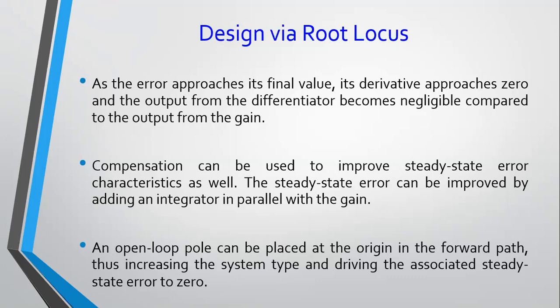In previous chapters, we had one section where we looked at transient response, which we just looked at. There was another chapter where we looked at steady state error. If you want to modify a steady state error, possibly because it's not equal to 0 yet, then you're looking at integration. You would add an integrator. For a PI controller, the P part is the proportional part, which is your gain. So you're always playing around with your gain. Fine, that's the proportional part. But if you want to correct for a steady state error, then you're going to use an integrator part.